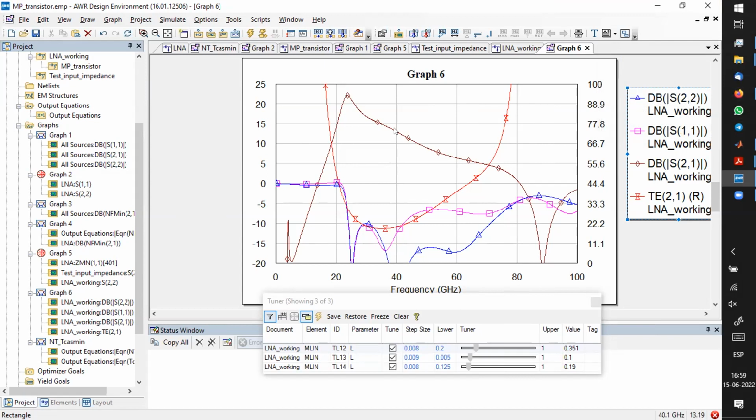So tomorrow we need to start adding those RC components and other stuff to get the gain down from that peak, which seems to be actually close to our band, which is not good, but I think we hopefully will manage it. And most probably, if you plot now the stability factor, it's unstable or potentially unstable on that peak area.